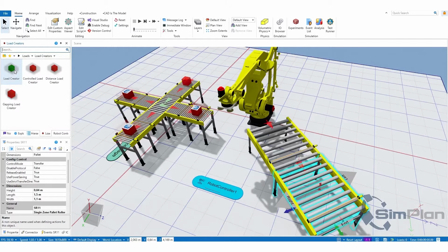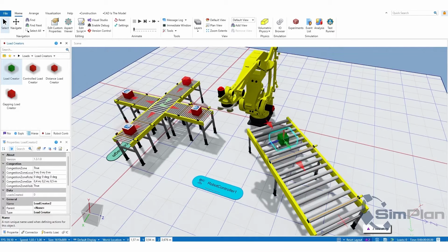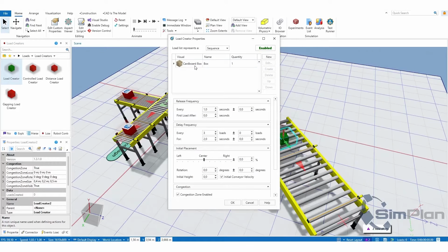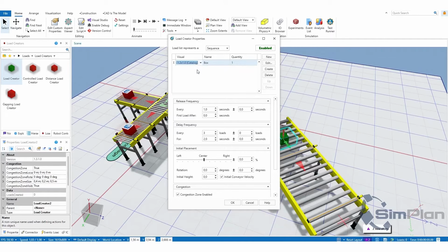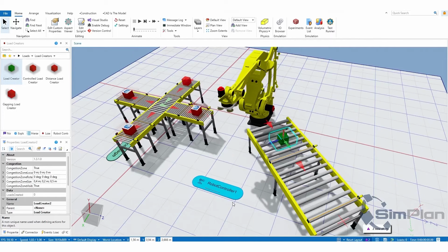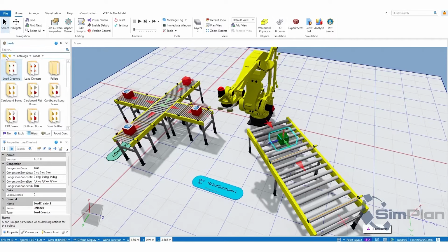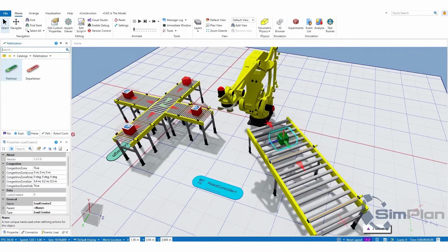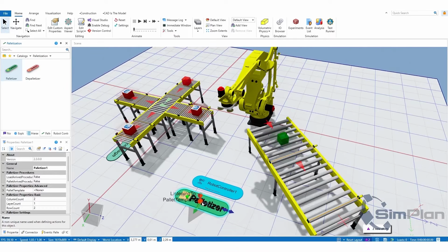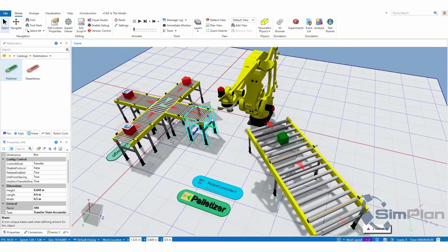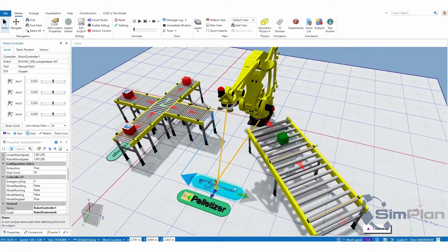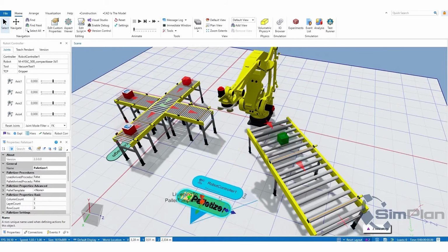However, CAD import and kinematics can also be used to develop your own robot modules and store them in your own libraries. A common principle in Emulate3D for logically linking components is to drag so-called visual references with the mouse. In this way, robots are linked to the associated controllers. For example, robot movements can be programmed analogously to reality using point-to-point or linear movements.